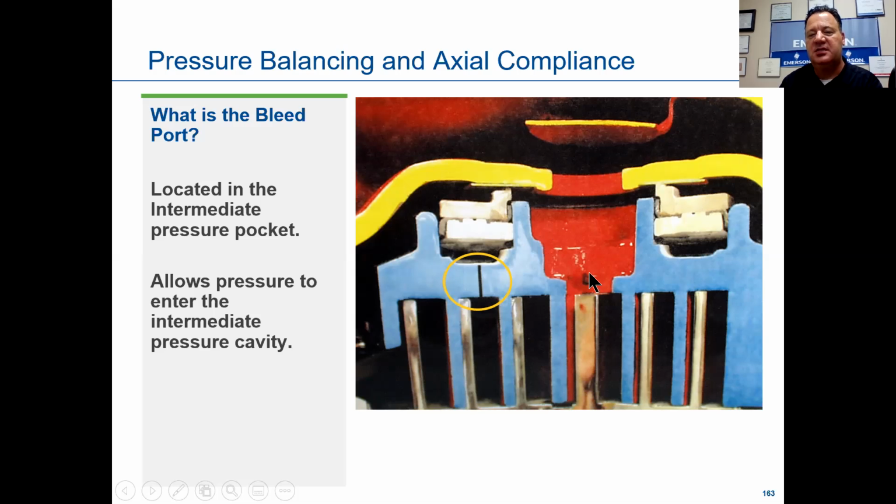So it isolates it, forcing it to go out the top above that muffler plate and at the top of the scroll compressor. If this were to fall down, and I'll get into that later on, this gas would then come around and re-enter that suction gas with the motor.